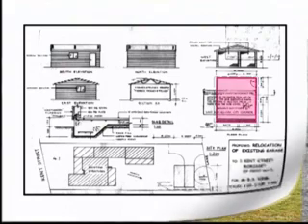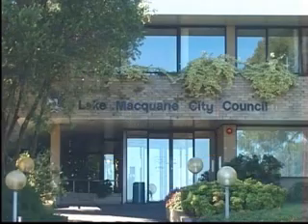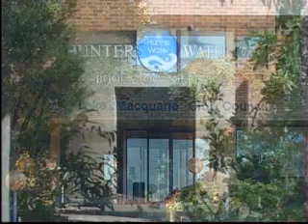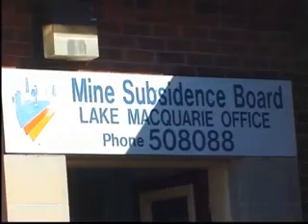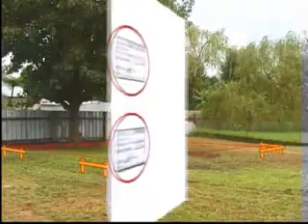Local council approval is necessary before construction can begin. Sometimes other authorities also need to give their approval. A check should be made to ensure plans are stamped and dated to indicate approval. It is good practice to become familiar with both the site and the plans before setting out commences.